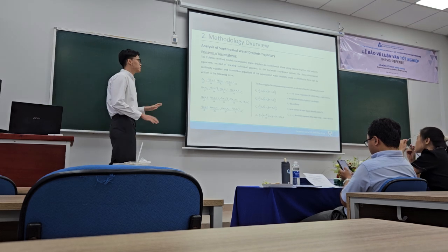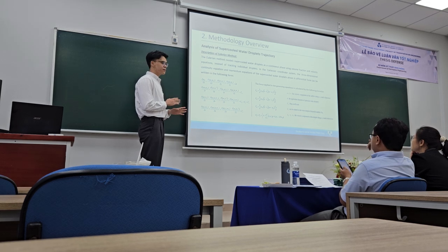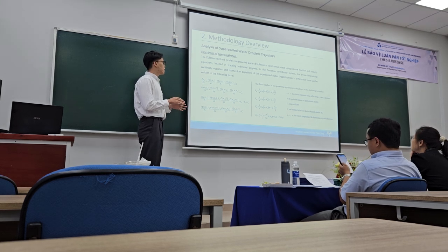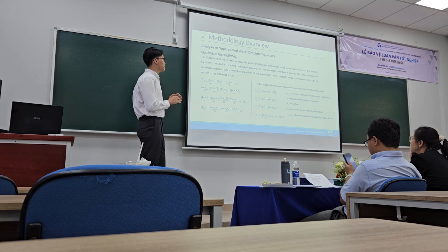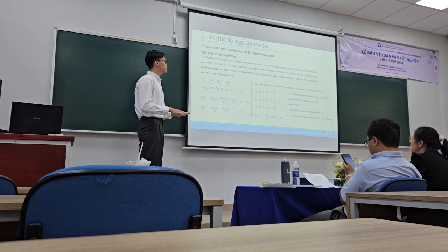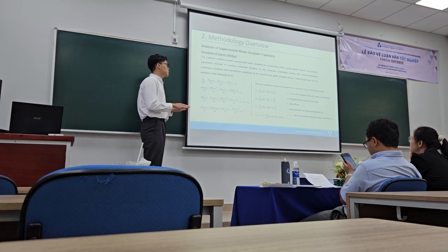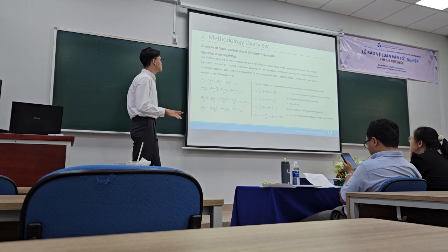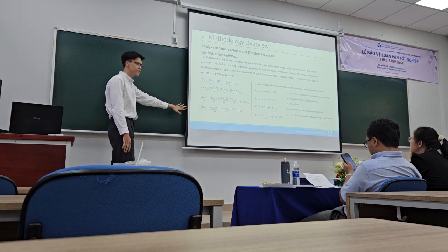Next, in this project we will use the Euler method. We have two main methods for researching droplets, Lagrangian and Eulerian. For this project, we choose Eulerian, which considers droplets as a continuous phase using the volume fraction. In contrast, Lagrangian considers droplets one by one, not as a phase. We will use Cartesian coordinates, with four equations because we have a 3D wing.